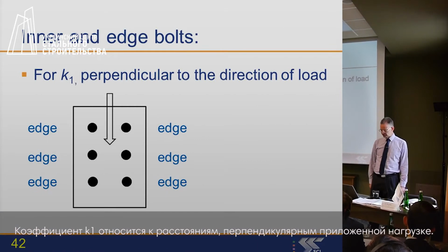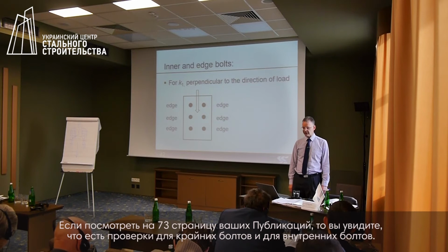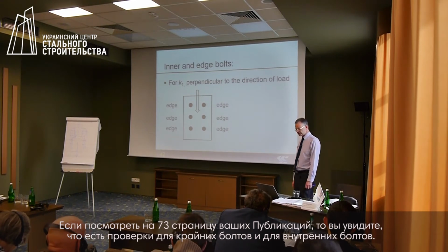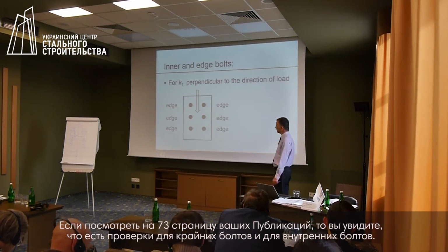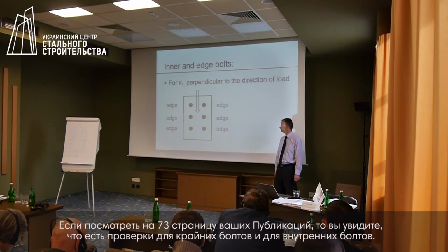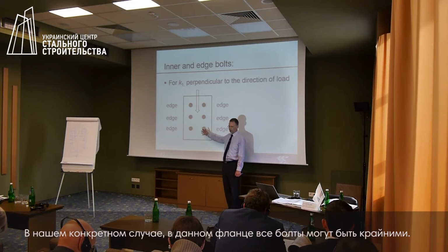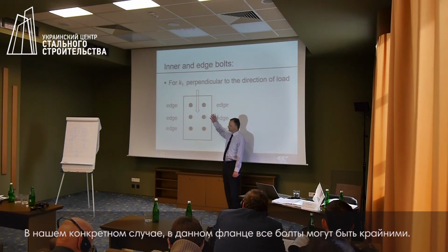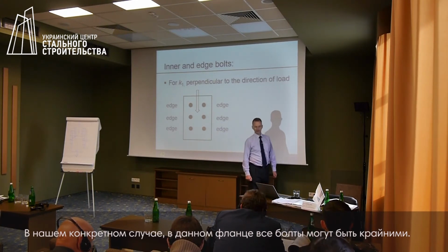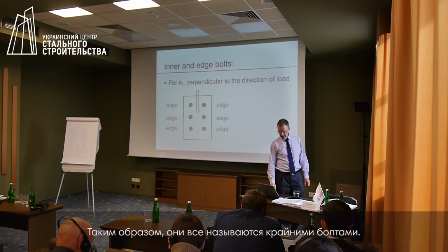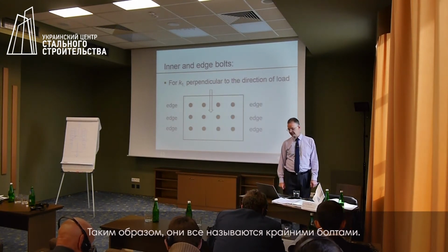K1 is concerned with direction perpendicular to the load, and if you look on page 73, you will find bolts described as edge bolts and inner bolts. In this particular plate, all of the bolts could be affected by the edge, so they are all described as edge bolts.